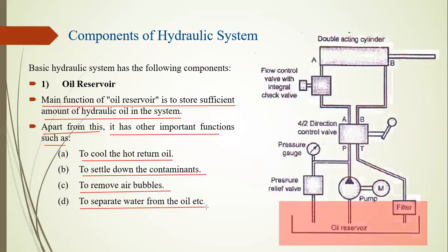When some oil is in direct contact with the atmosphere, moisture is added into the hydraulic oil, creating water particles inside the oil, so it is necessary to remove the water from the hydraulic oil. So the hydraulic reservoir tank has other functions: to cool, to settle down contaminants, to remove bubbles, and to separate water from the oil.